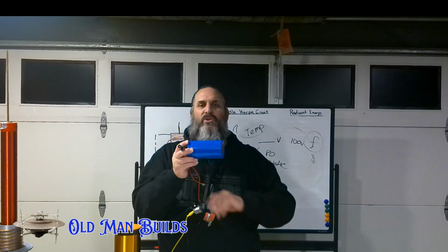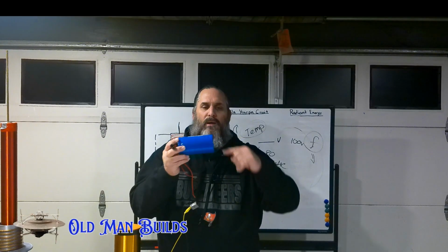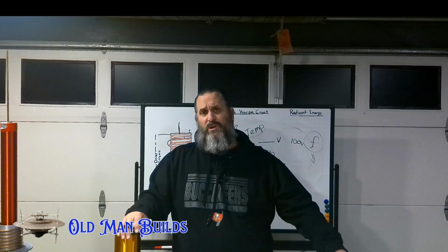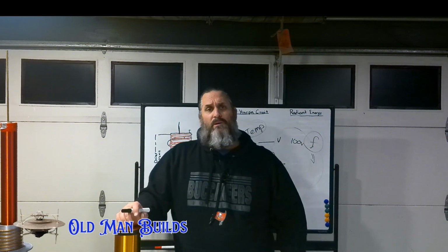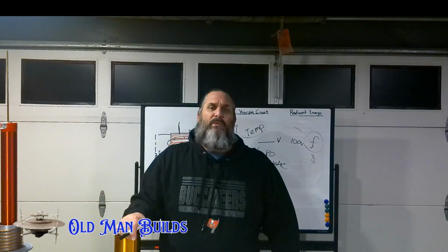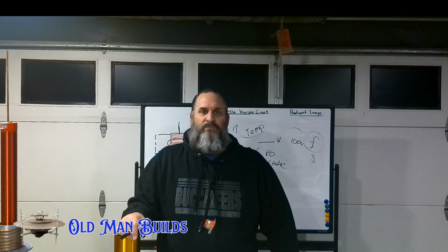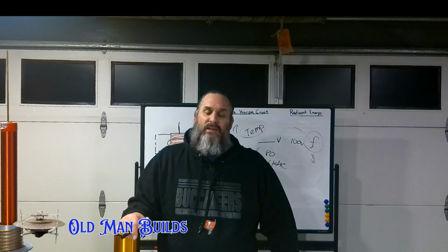Therefore, the outside took on a little more heat. Now I'm getting voltage fluctuations. You know where else you get voltage fluctuations? Try creating an AC flyback without putting in mineral oil and taking out all the little bubbles. Every single bubble that has air in it is going to give you a fluctuation in that transformer.